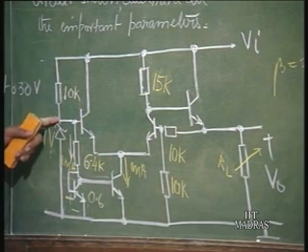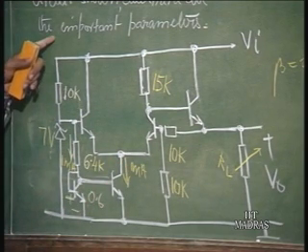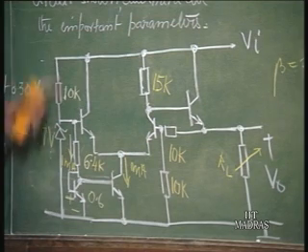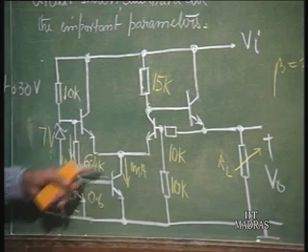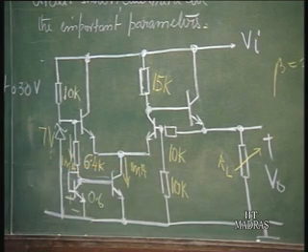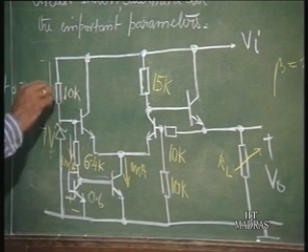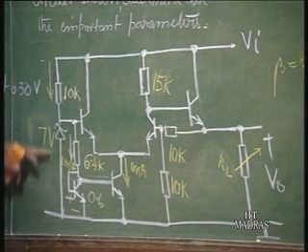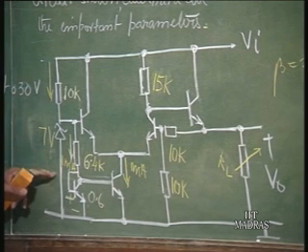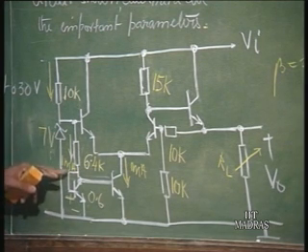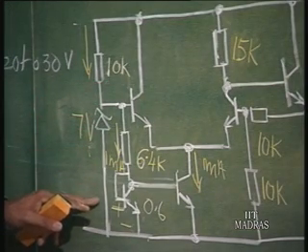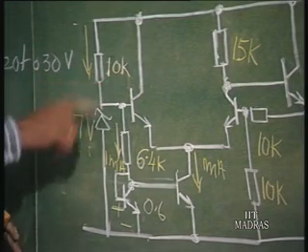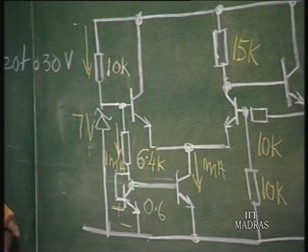That is made independent of the input voltage variation. If we had connected this here, it would have varied. We do not want that to vary. So, this current is made constant, bias current is made constant by connecting it here. So, this current of course keeps varying here. This is the bias current needed for the Zener. Please remember, this has to be greater than 1 milliampere here, so that some current is left for the Zener. This current is going to supply the Zener as well as this 1 milliampere.